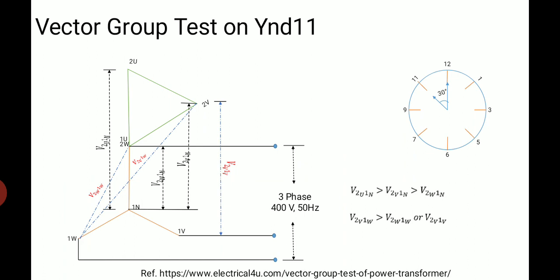It means that DD0 can be connected in parallel with a transformer which has 0 degree phase displacement, whereas DY6 can be connected in parallel with a transformer which has 180 degree phase shift, whereas for group 3 and group 4, DY1 and DY11 can be connected in parallel after interchanging the connections to obtain similar vector groups.